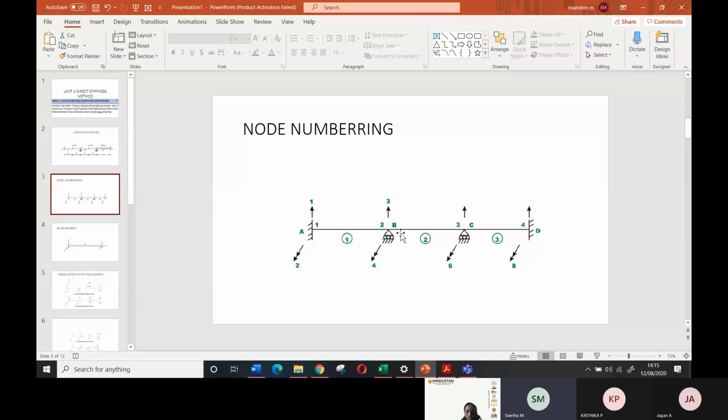So you are applying some moment, and you understand what I'm talking about: the torsional moment. When the cloth is in the horizontal direction, one hand twists clockwise and the other hand anti-clockwise. Hereafter, when you do that at home, you just feel it, and tell your mind that you are applying a torsional moment to the cloth. That's why the water gets squeezed out. A practical beam can also be subjected to torsional moment: if one end of the beam has a clockwise moment and the other end has an anti-clockwise moment, it will be subjected to torsion.